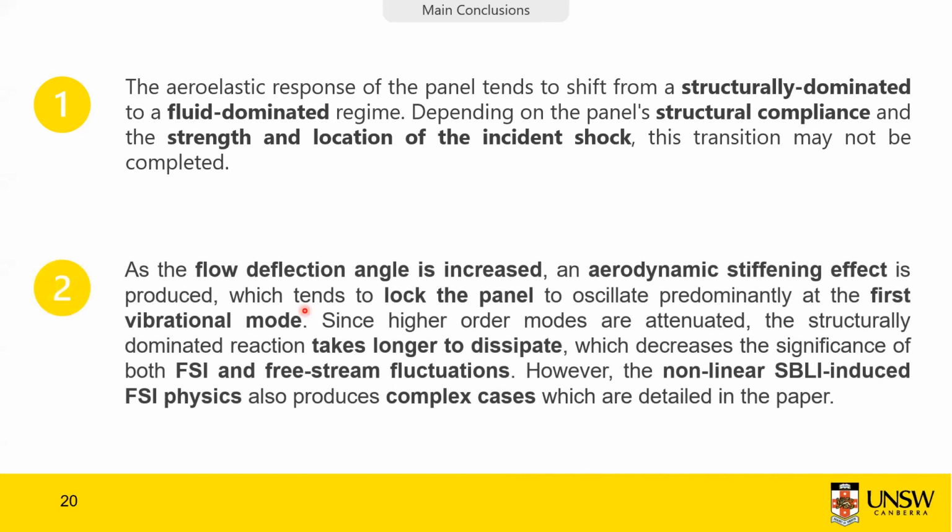Since we don't have the occurrence of high order modes, since we are attenuating them, the structurally dominated reaction takes longer to dissipate. And then that decreases the significance of both the FSI and the free stream fluctuations. But this is a bit complex, and the nonlinear shock boundary layer induced FSI physics is portrayed in detail in the paper.